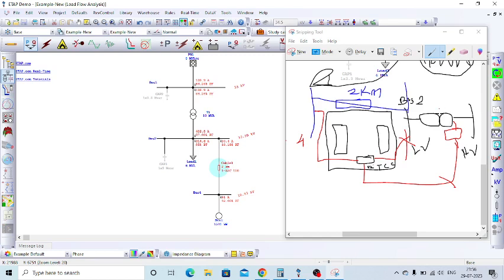In some specific cases, if we need to regulate a bus other than the immediate transformer bus, that is bus number 2, and here the other bus is bus number 4, then we have to monitor the voltage at bus number 4 through this RTCC panel, and there are some challenges involved in this cable.